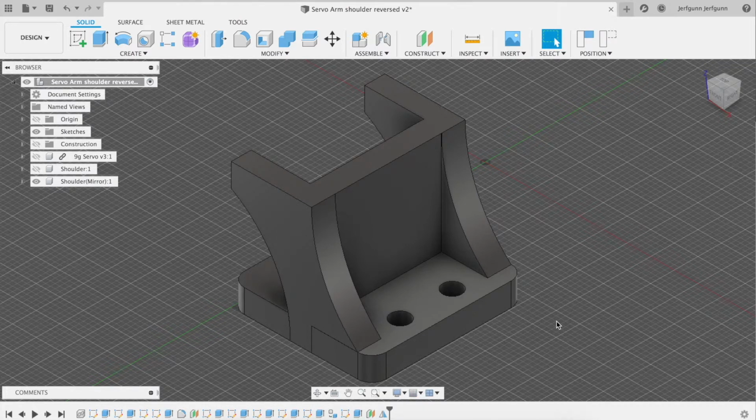And one other interface configuration I find really useful and I would recommend to you is to change the orientation of the z-axis. Now, if you're working in any digital fabrication technology, any common technology like CNC or 3D printing, the z-axis is vertical.